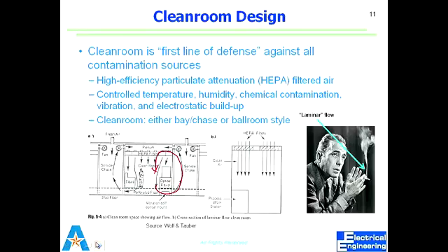What does humidity have to do with it? Photoresist essentially is a very, very fundamental process that we do. Photolithography, in which we apply photoresist on the wafer. That stickiness of resist, or its exposure, or its development is highly impacted by humidity. I've seen it many times. Students would say, "Oh, I did lithography like 5 times and nothing worked." And I said, what was the humidity in the room? Every photoresist, every process has a humidity range that it will behave in. If we are above or below, it's not good. It's not going to work.